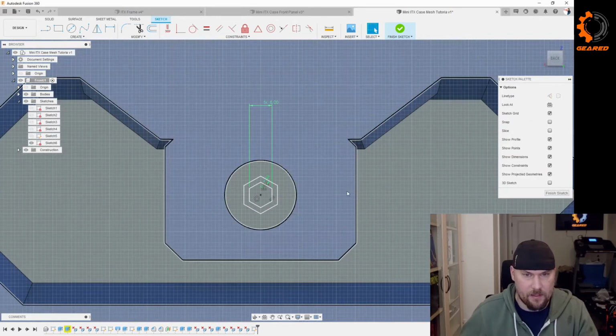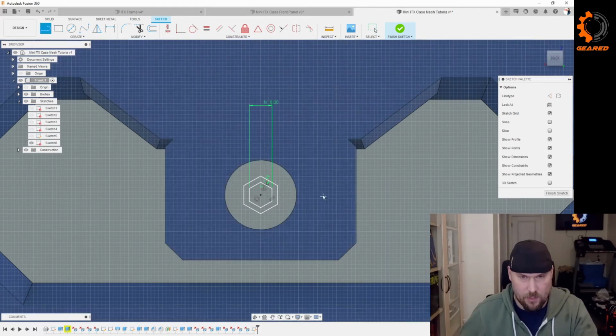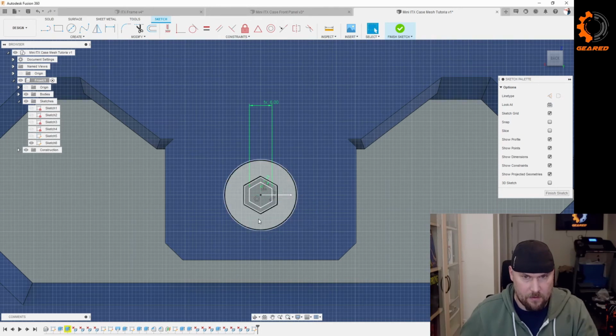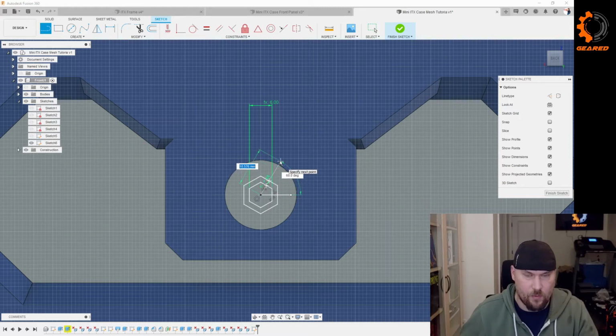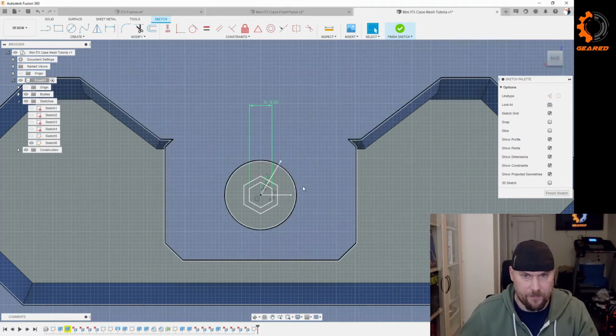Okay to that. We then need to create 2 lines for our mesh direction, one going out this way, and another one coming up this way. And these will be perpendicular to the sides. This will give us the direction for our mesh.